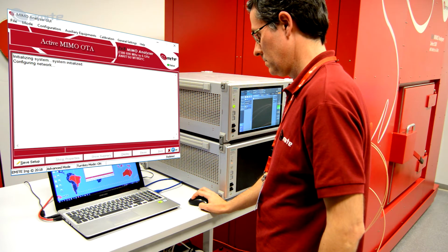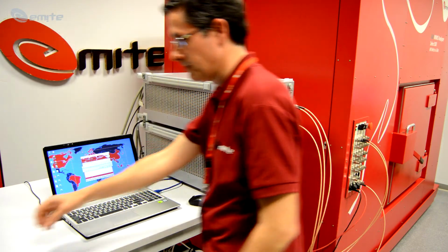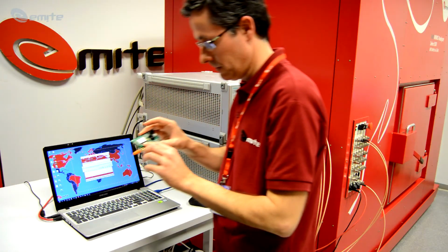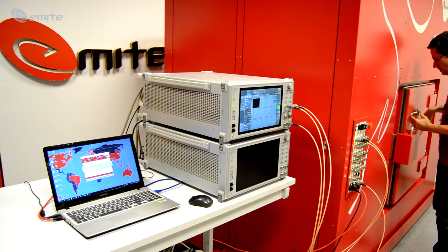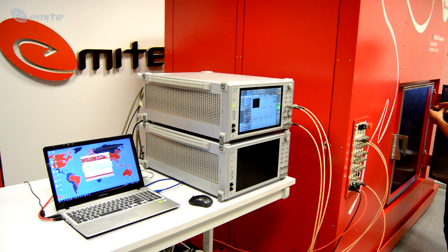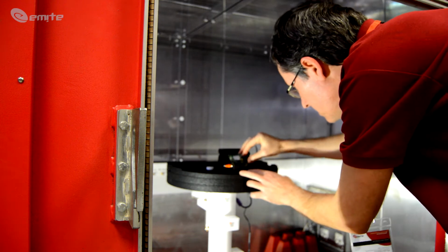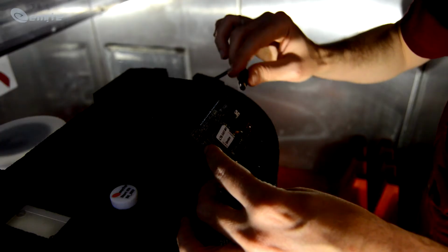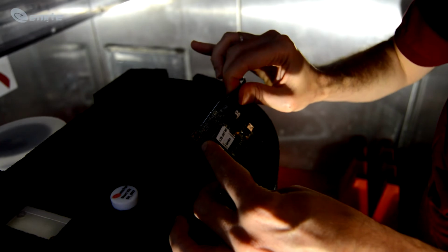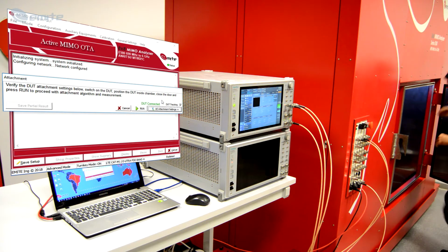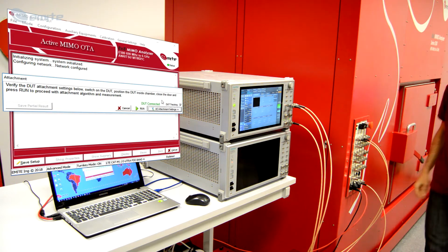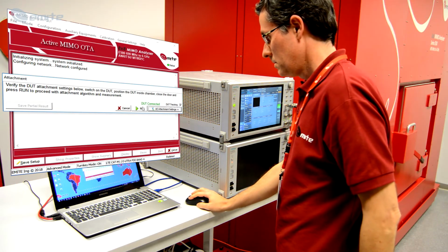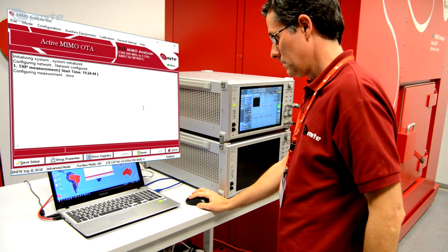The test system will be initialized and auxiliary equipment properly configured. Tests will be performed in a fully automated manner using the set sequence. Place the wireless IoT device on the turntable inside the chamber with a test SIM card and connect it to the power supply on the turntable if needed. The device will get attached to the test network within seconds. Once the device is connected, click on Run to start the batch of OTA tests. A DUT attachment window will pop up for the first and only time.